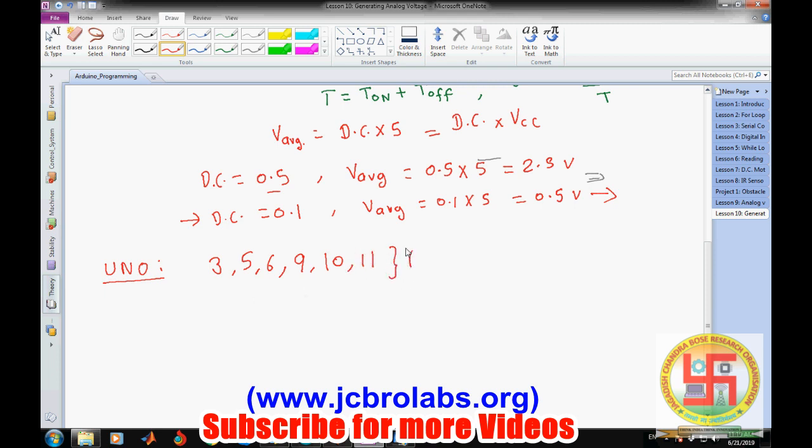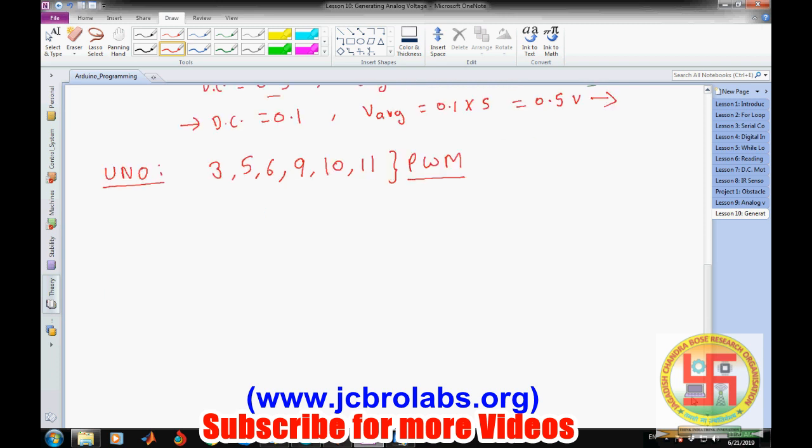These are the PWM pins at which PWM is generated, and on all of these we can generate a variable voltage just by doing a small amount of programming. Now there is a command in Arduino which is used to generate this, that is analogWrite. It takes the pin number and the value.